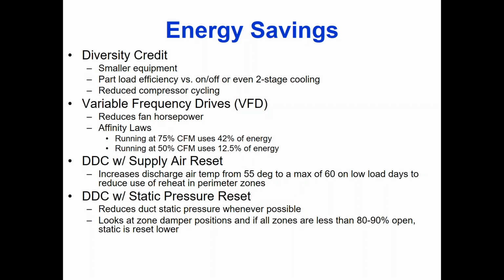Both supply reset and static pressure reset are easy to do with DDC controls. It is a standard control function that every DDC manufacturer can do. It's not proprietary, but you need to ask for it up front. If you build the building, set up the controls, and everybody's done with the job, and then you ask the controls guy for that, it's going to be an extra. If you ask for it at bid time, it'll cost nothing.